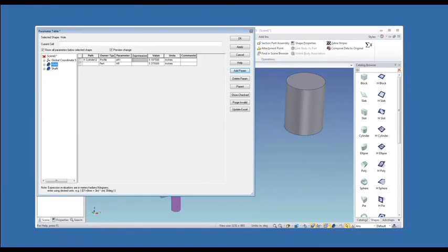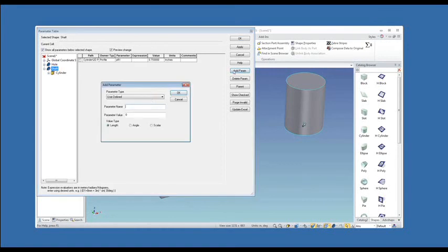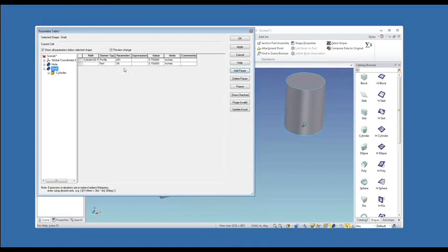And you remember from our driving parameters, you have to have something at the part level, and that's what we're going to do here, because in 2015 the attachment points only work at the part level. In 2016 you'll be able to apply attachment points at the feature level, but that's not implemented quite yet. So we got that set there, and then I go to my shaft, and I want to do the same thing here. The shaft radius is 0.75, make that equivalent, and we're okay.